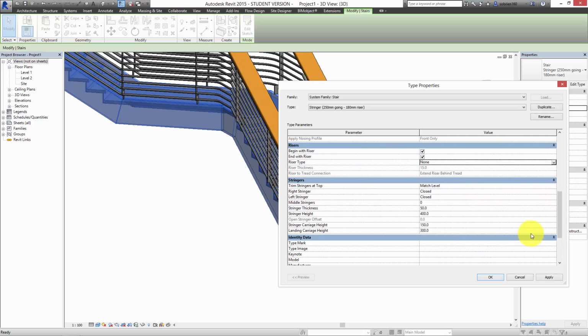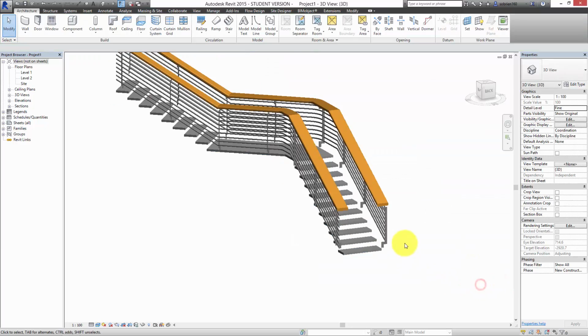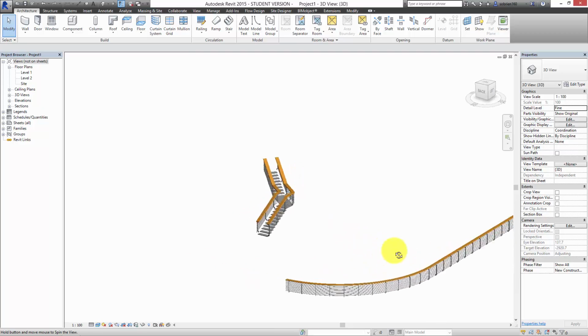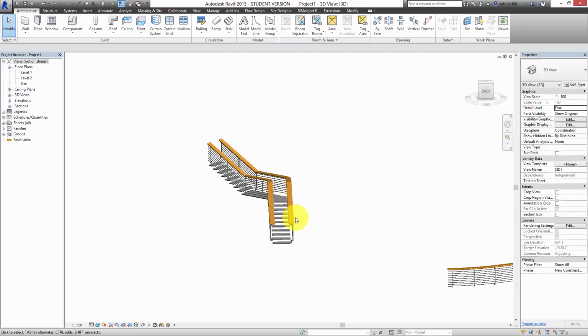So we've got no face to the steps anymore, which is what the risers are. And where we come into stringers, I'm going to come down here and say we don't want any stringers either. Just change that to none. We don't want any of the standard stuff in there. So now we got something like that as the basis for the staircase.